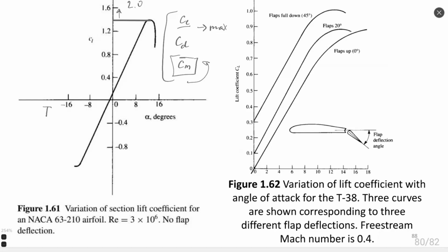There are some very performant airfoils with very high lift coefficient, but they also have a high drag coefficient, so the lift to drag ratio is not so good. There are airfoils with a very good lift to drag ratio, but they have a very high or very low negative momentum coefficient. Also not good, because you need to put additional mass on the tail to compensate this momentum. So always pros and cons, advantages and disadvantages. There is no aerodynamic structure which is perfect for all possible applications.